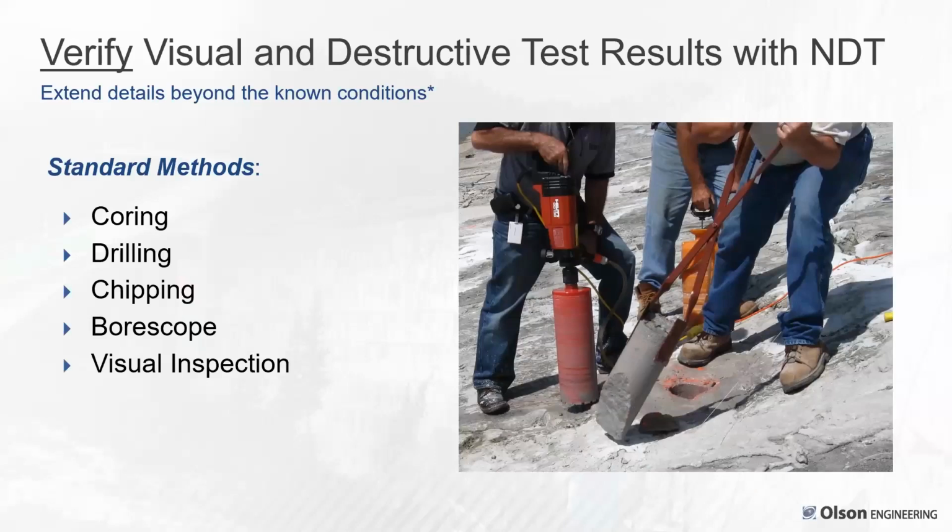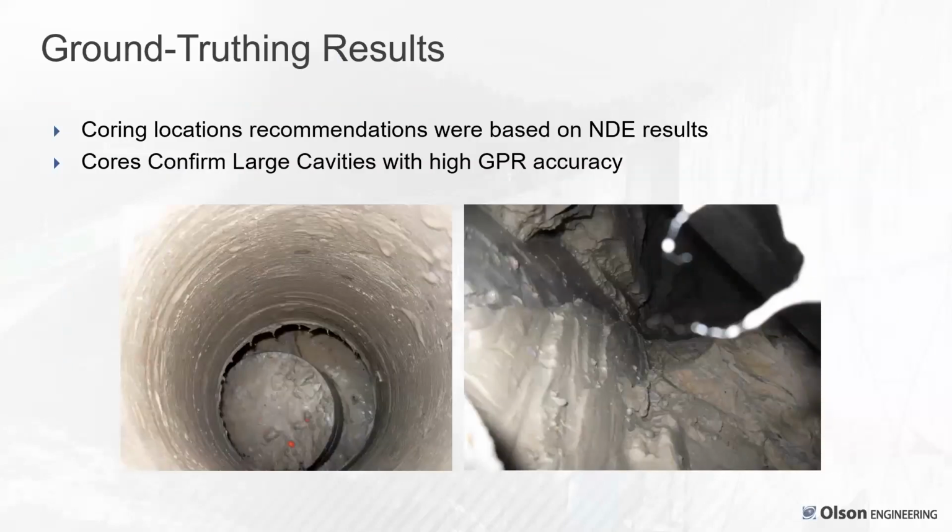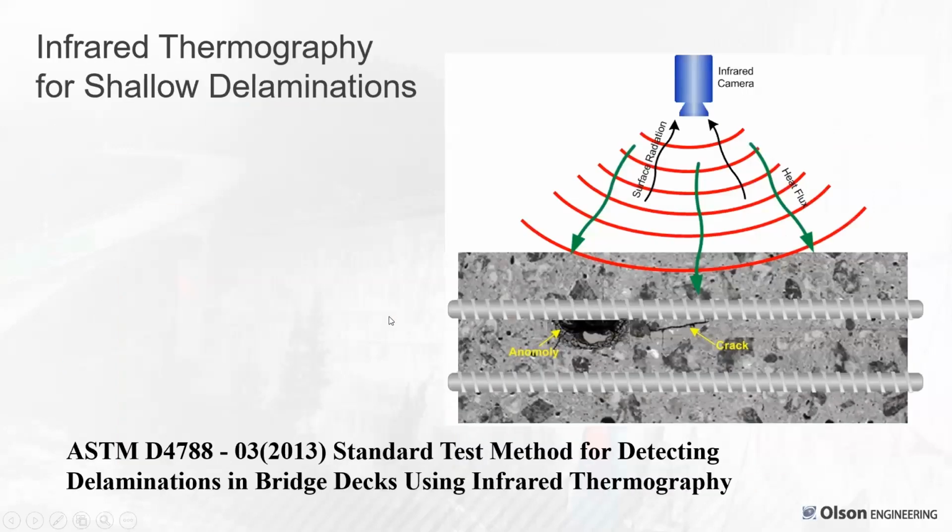So this shows that you take the cores out of it. Interesting enough, most of the time we got the cores recovered just fine. Really big voids, the core stayed in the hole through that soil cement liner, but you could still measure it and confirm the thickness of the void. It was just proof positive, and indeed there was a problem. So it correlated very well, again, helping to assist in remediation efforts.